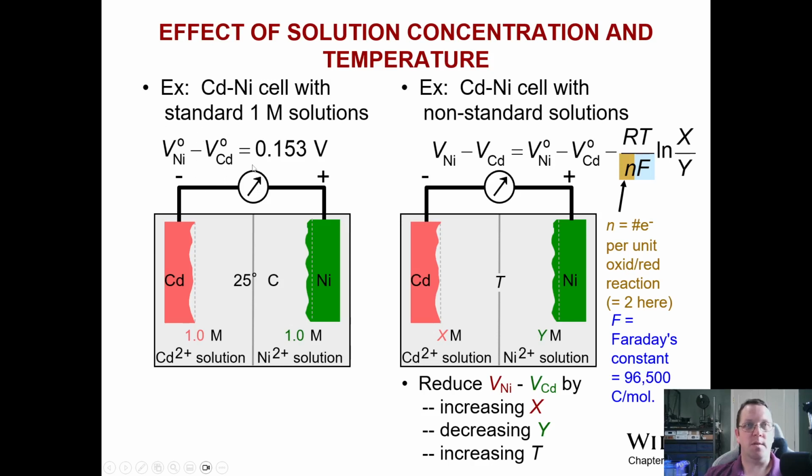A lot of things have been nickel cadmium, nickel metal hydride for rechargeable batteries going back a long time. So this kind of 0.15 volt per cell difference is much more common than it used to be. So some of these batteries are fairly low in terms of overall voltage and definitely low in amperage that they can produce, but they don't have to be extreme in order to run really, really small electronic loads.